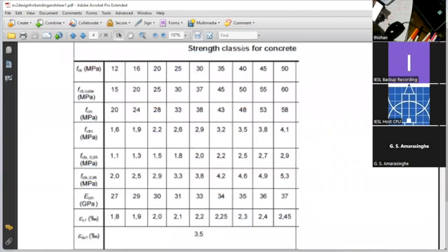The allowable stress is 27, sir. And then 27 plus, we have another about 2.2, 2.7. So we are allowing a stress range close to 30. It's a huge stress range for the stressors. And that means, you might be able to use a smaller section and go for an economical design.